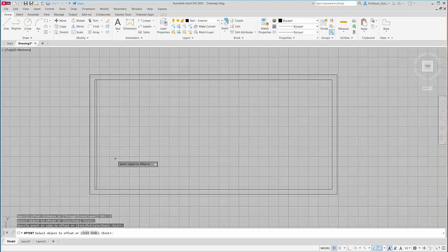It does the entire length of the line. Then the doorway opening there is 0.61, so offset 0.61. And then the next value is 0.91, so offset 0.91. And then the wall thickness is 0.11. These are all in meter values. So I'll select offset, type in 0.11. And I've drawn that room. Now you really don't see that room until I do the next set of lines.